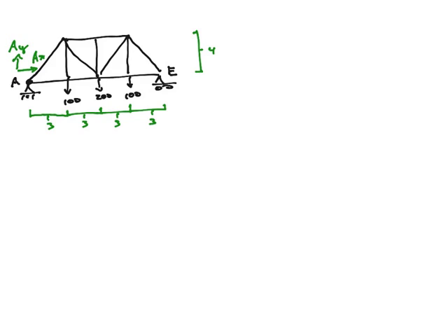Usually, if you can't tell by looking at the picture, engineers will guess the reactions to be in tension, tension meaning away from the joint. And then if you happen to get a negative, oh shoot, it was compression actually, it's going the other way. That's fine. But if you can guess it, it's best to try to guess it.